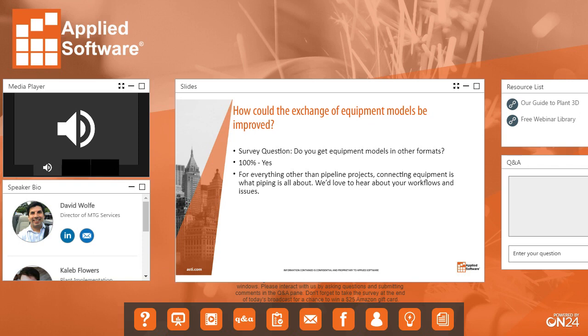about your equipment modeling. Yeah, I think the Inventor shrink wrap functionality is just top shelf. You can bring in some really complicated stuff with all those internals, and the Inventor shrink wrap will just make that all go away. It does. Yep. So Ralph's comment was that sometimes it's quicker to just model things simpler with your right nozzle locations than to try to bring the vendor stuff in.